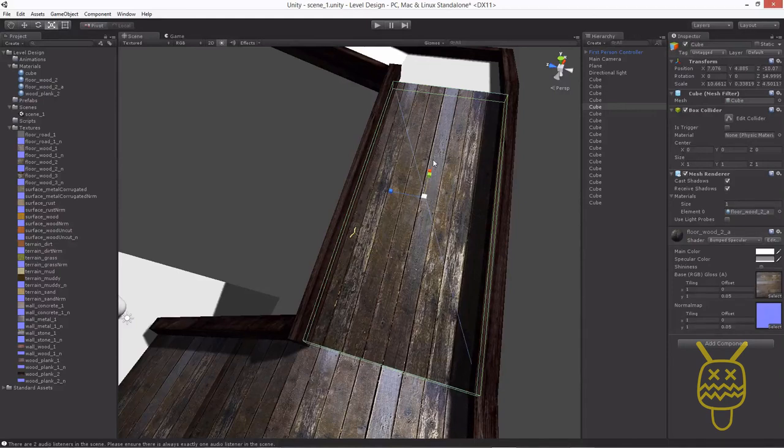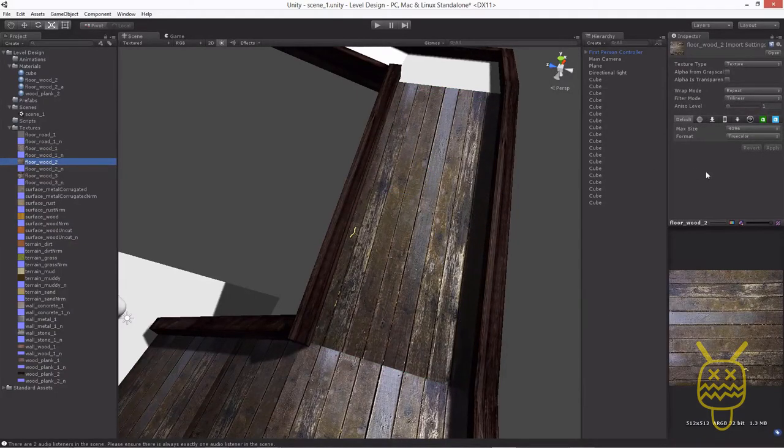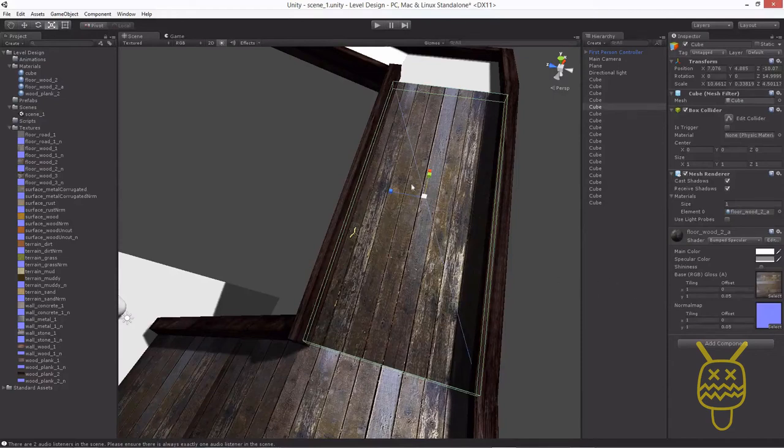Now this is one of the catches though, if you want it to go the other direction, you either have to rotate your object and then place your object going up this way, or you're going to need a texture that's actually rotating to the side. If you notice, this is one of the catches with Unity, that the texture itself, you actually only have a UV coordinate, you don't have the W coordinate on it. So for this one, we're just going to need to use another texture that actually goes that direction for it.